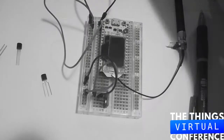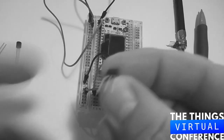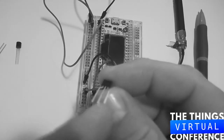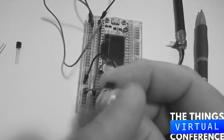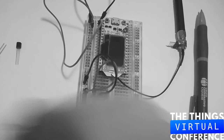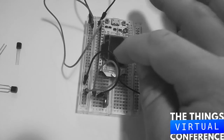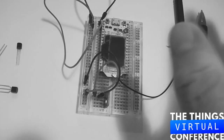Let's just take a look at that on our sensor. So there is a flat side, and I'll try to put the flat side the same way, and then I have pin 1, 2, and 3. So they are numbered, and labeled on the data sheet, and there you can find the connection. So ground to the ground at the microcontroller, and VDD to the power, and the middle one, that is the one wire connection. And many microcontrollers, you can decide which one you want to use for one wire. And I would say with this Heltec, use 17. That's one possibility. You can use 12 or 13, the pins or GPIOs.